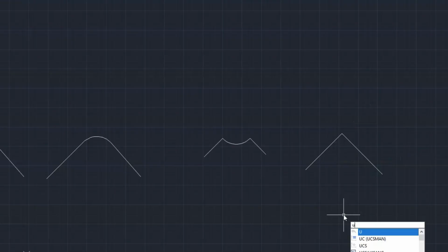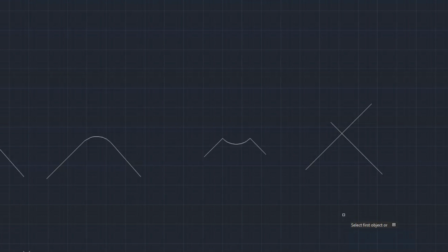But we now want to disable trim. Using the same settings, 50 radius and disabled inverse arc, we see that the fillet was created without trimming the ends of the lines. Finally, let's use the fillet on a polyline.